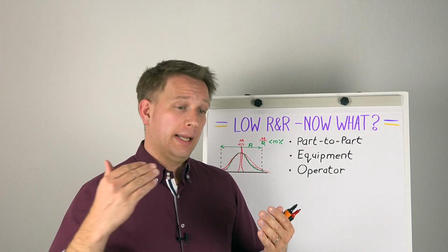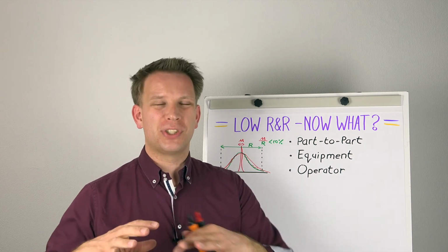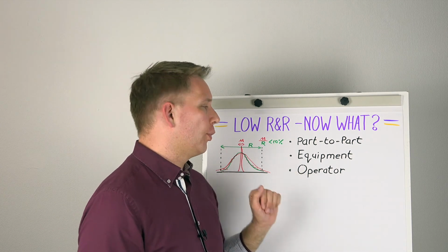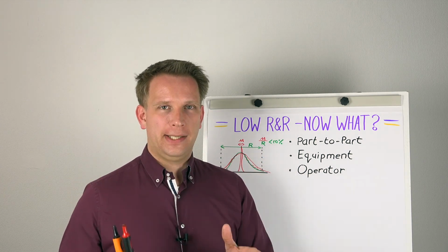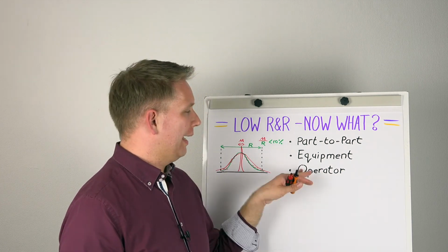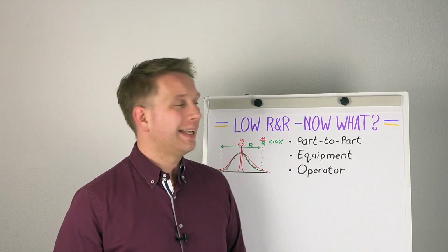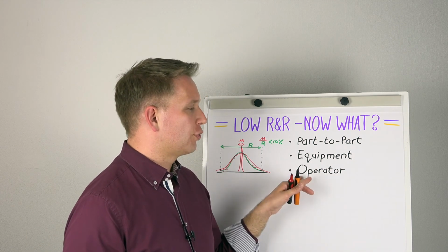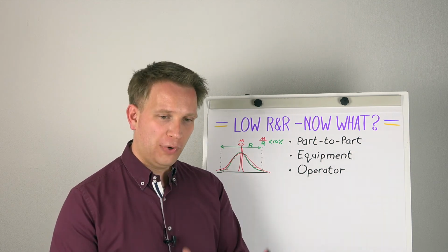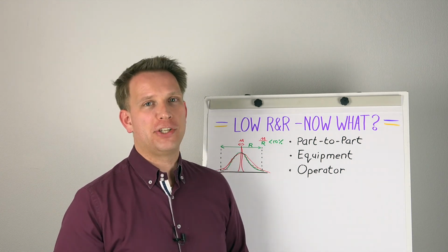Weather or maybe a wrong calibration before you start doing the measurements, such type of environmental factors can really affect it. Although if you do a nice and tight R&R study where you do one calibration for everyone and also just try and do it with the same batch in the same circumstances, then we're really looking at training and explanation of how exactly to prep the sample and how to measure and how to interpret the measurement.